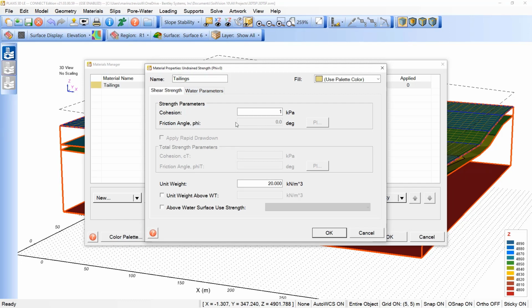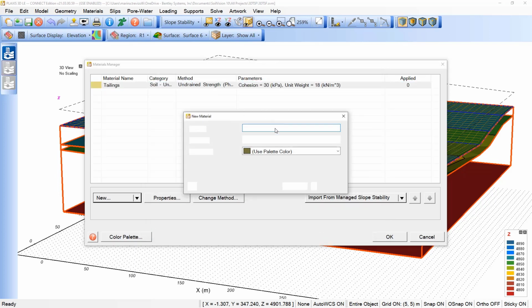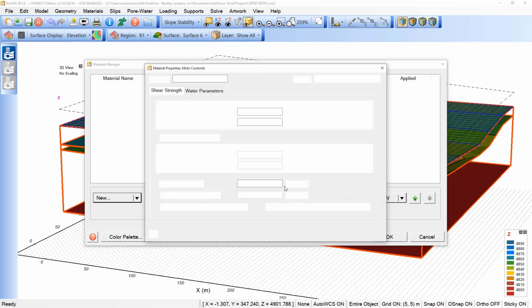And in this case, you can see we don't have the friction angle. And I will define the cohesion. So following the tutorial, I can define here the properties of my material. By doing this, I'll click OK, and I'll create the next material, which refers to the dam structure. The dam will be represented as a Mohr-Coulomb.